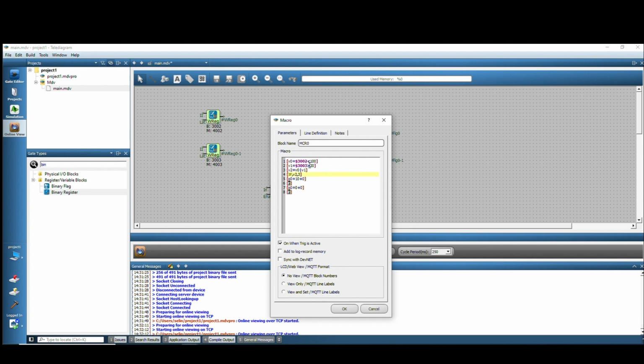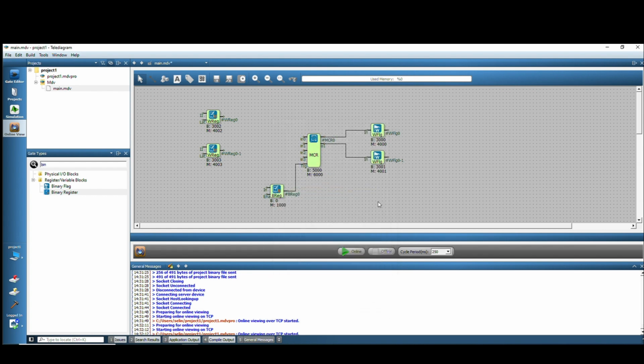Therefore, we put two different ends to sustain this loop. If the if condition is met, it will write 10, if not, it will write 0. And we'll start querying again from the first line as soon as it sees the end. Until when? Until the trigger time comes. If you don't say work while trig active, it will update its own software loop according to any change and change the output status.